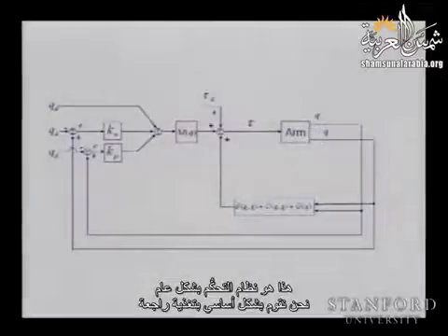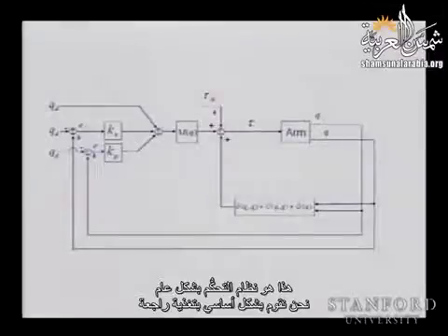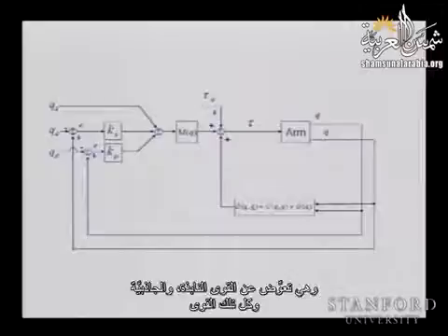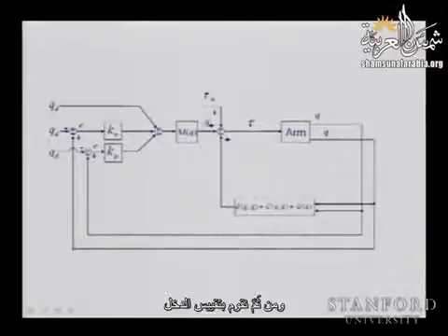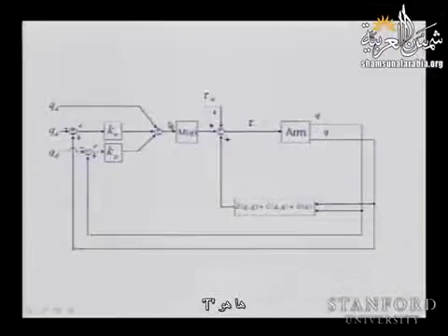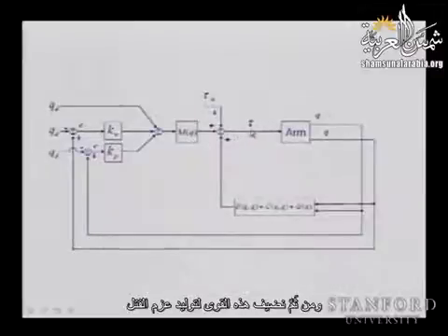So this is the overall control system. Basically what we are doing is a feedback that is compensating for centrifugal, Coriolis, gravity, and all these forces. And then we are scaling our input. So this is torque prime. It's scaled by m hat, and we are adding these to produce the torque.